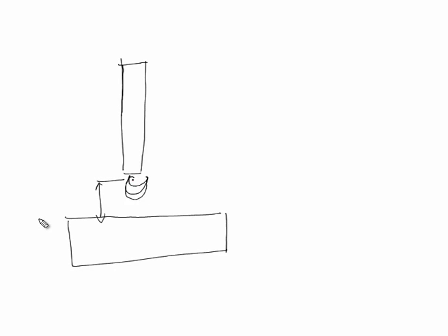As melting takes place gradually, this drop grows gradually, and because of the closeness of the weld pool to the electrode tip, as soon as this molten metal drop touches the weld pool, the short circuiting stage is achieved.